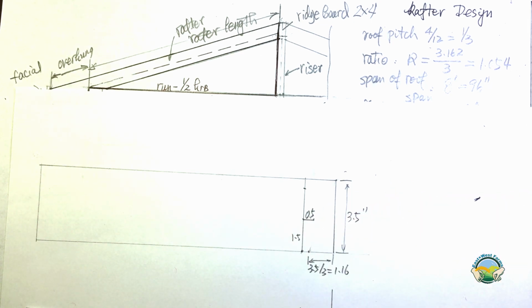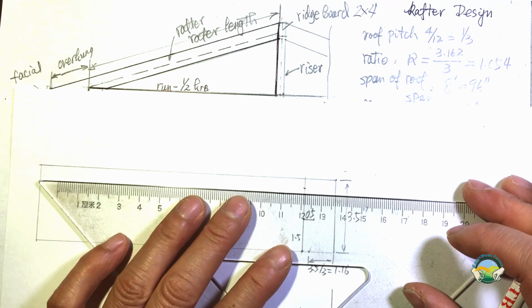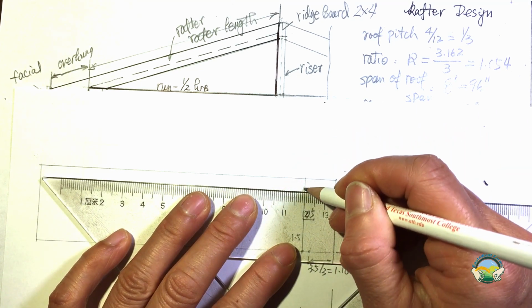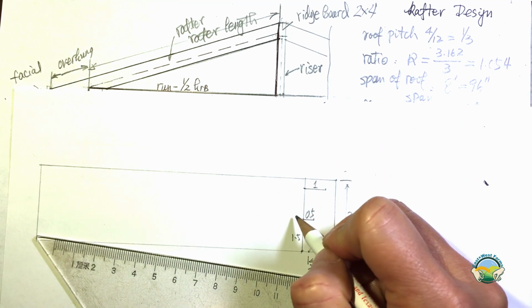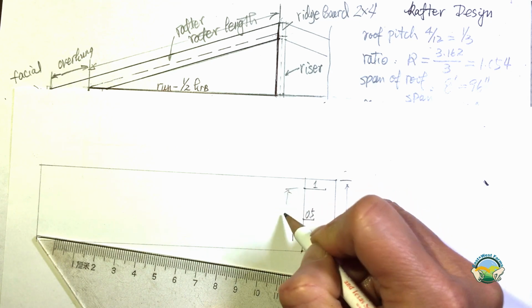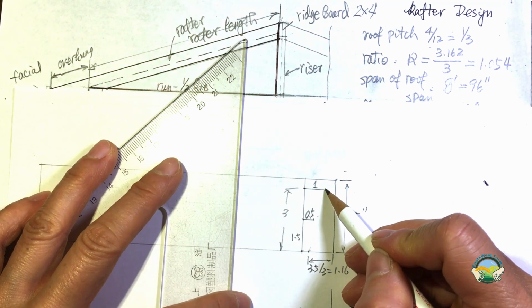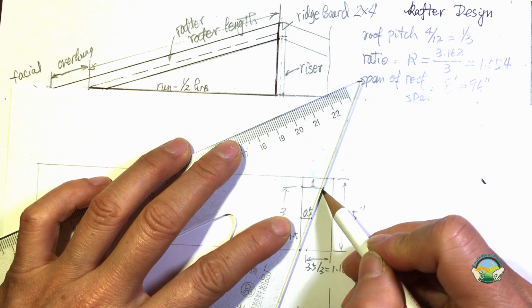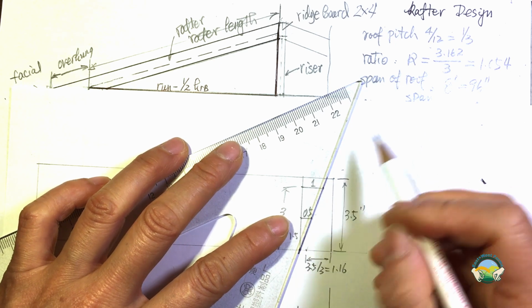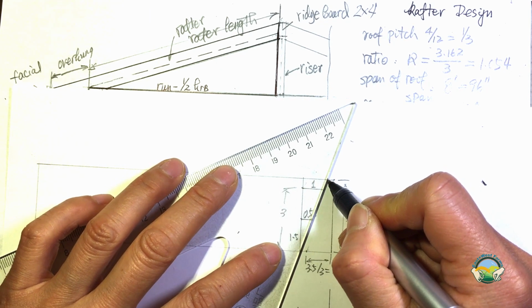That gives you a ratio of 1 to 3. The same thing for the 3 inch mark. Then you draw 1 inch, so that's 1 inch, and that dimension is 3 inch. And so now you basically have two points, this point and that point, and that will define your plumb line. So that's your cut. I will mark it using a different color to show that's your plumb cut.